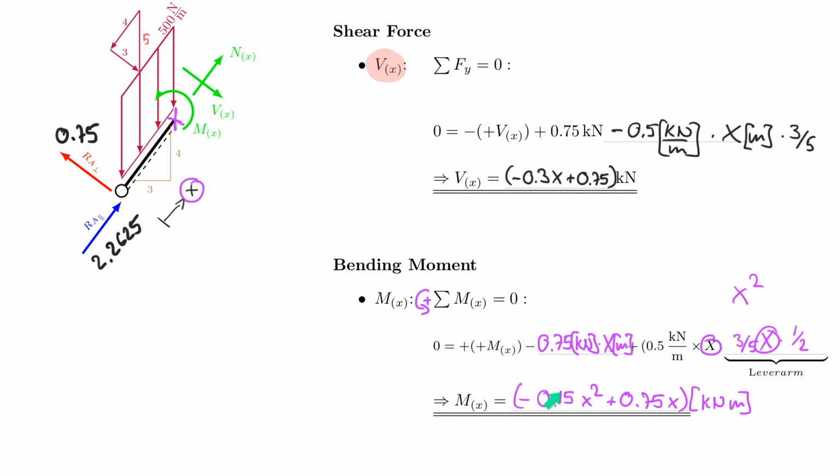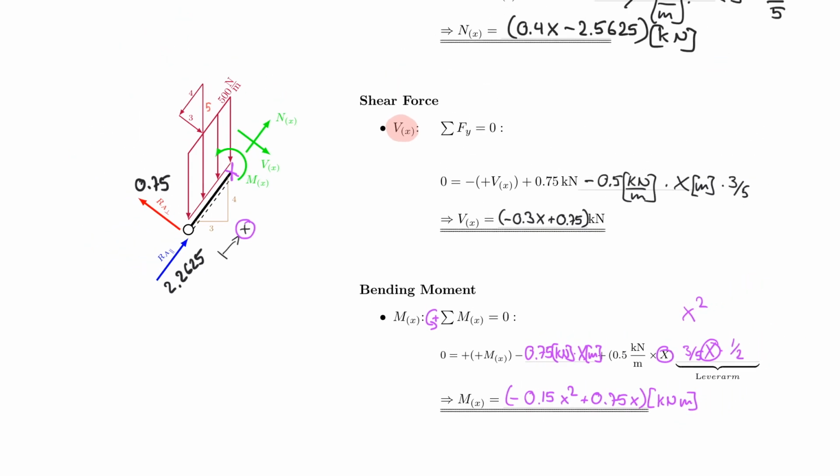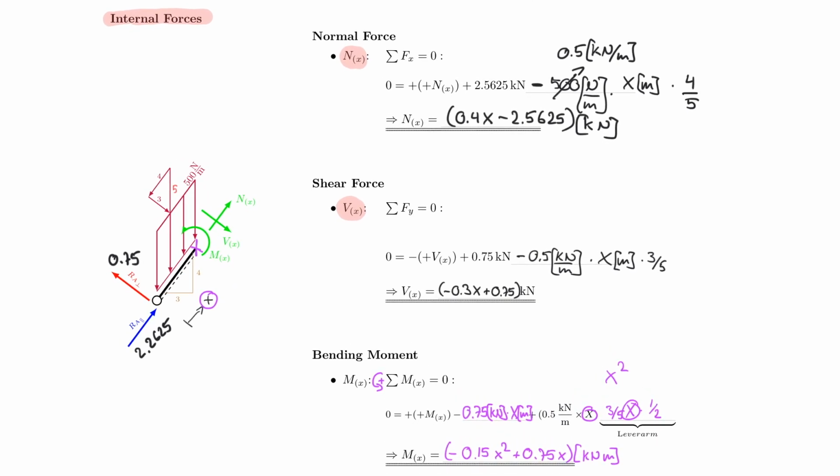Also, what's true is that this equation, the shear force, is the derivative of the moment. And what have I done now? I have on this page effectively my internal forces. And in fact, I don't just have the internal forces, I also have functions for the internal forces for my roof structure. Be careful, it's only for the left side of the roof structure, but with deep thinking, it's probably easy to also extend the knowledge to the right side. Just don't do it blindly, because the right side obviously is similar, but also with a few tricks. But we will cover that now on the next page.